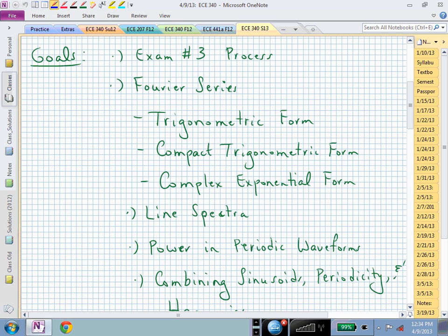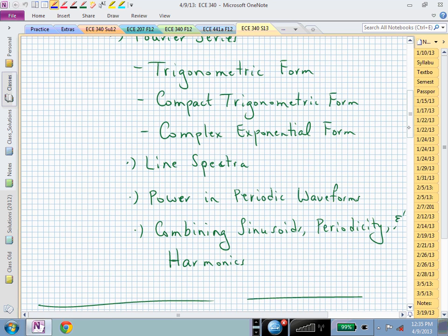These X's, we're breaking those up into sinusoids, and we now know in sinusoidal steady state how to find the output. We just evaluate the system at the given frequency, and that will give us a complex number. That complex number now tells us how the magnitude and angle are influenced in that component of the input at the output. We'll preserve the frequency. It will just now get amplified or attenuated and shifted in time based on how the system shapes that signal. And that shaping of the signal could appear in all sorts of contexts.